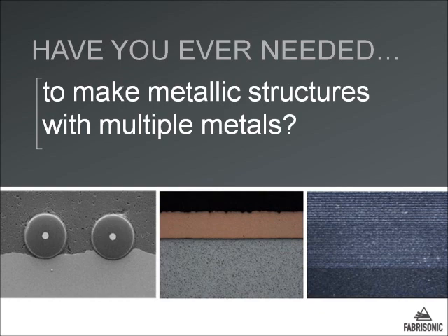The example on the right is a custom material for armor properties. It's custom designed using layers of aluminum and titanium. As you can see, through thickness we vary the ratio of aluminum titanium to create a material with very specific mechanical properties. The properties at the front of this plate are different than the properties at the back, intentionally to create a good ballistic absorption material.